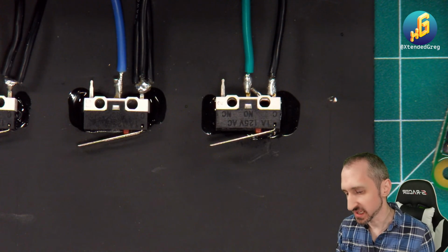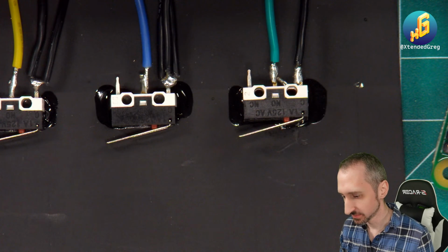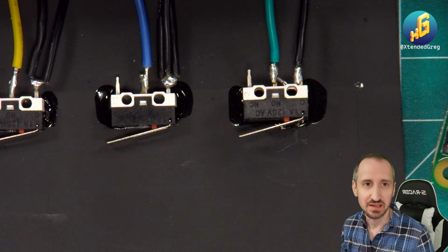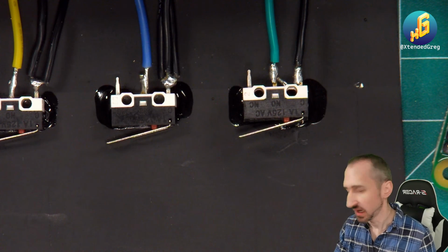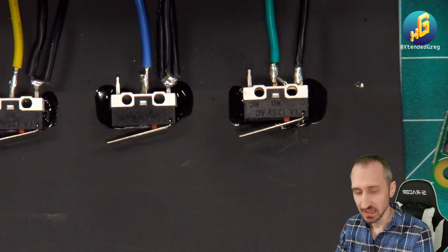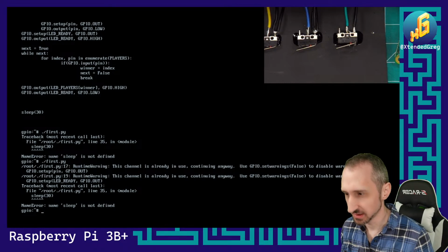So we could actually just correct this now just by moving over the wire. And I'm thinking about just doing that so that I'm not causing problems with this whole thing. The other option is we can actually reverse it. So right now this is holding it low, but I like the idea better of having it be a falling edge as opposed to a rising edge, just because we don't actually know how fast the voltage would go up. We do know how fast it would go down, because it's a lot easier to drain it than to fill it. So that sounds weird, but it's one of those things.